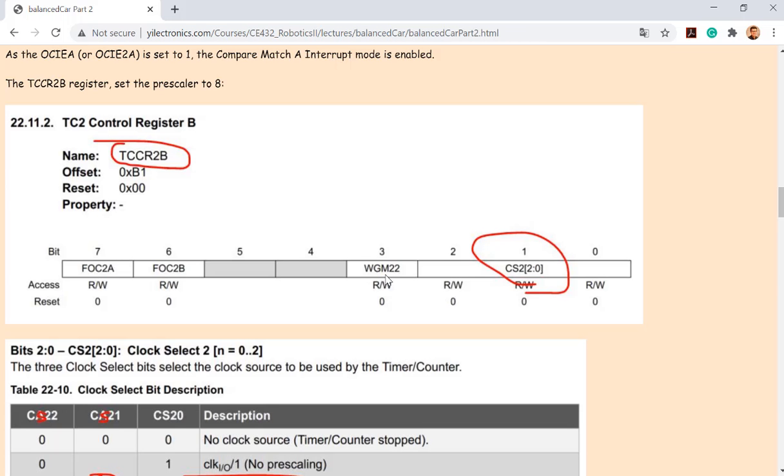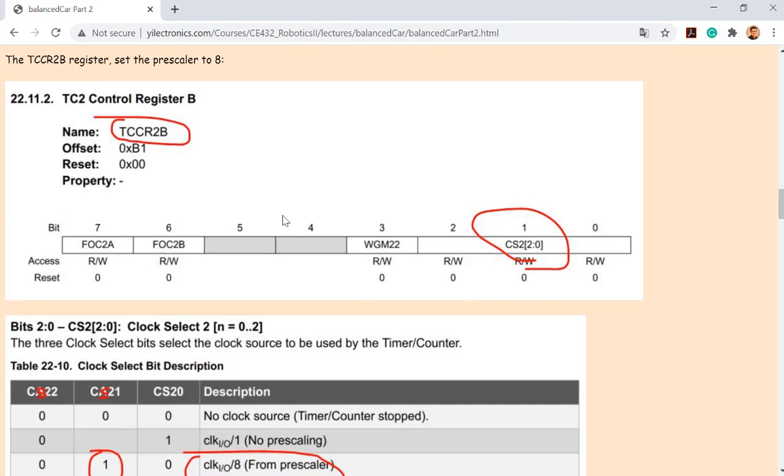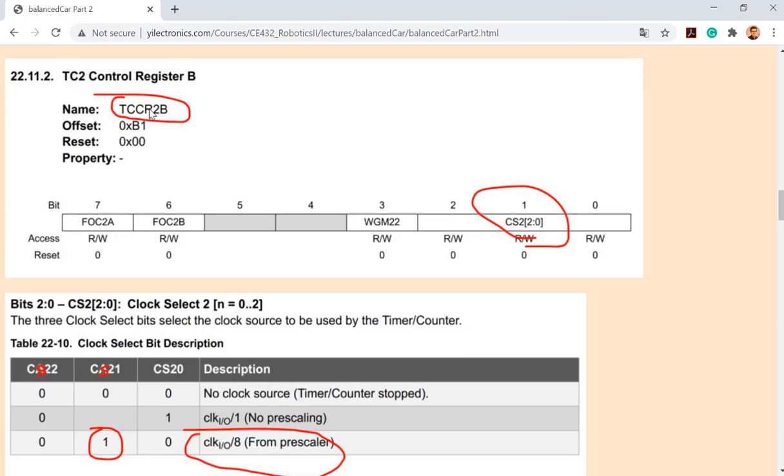Okay, let's come back to the interrupt. So there's a control register for the interrupt. It's just the memory, 8 bits, right? All the registers are 8 bits in your 328P microcontroller. It's an 8-bit CPU. And so every byte in there, so that's 1 byte for this register.